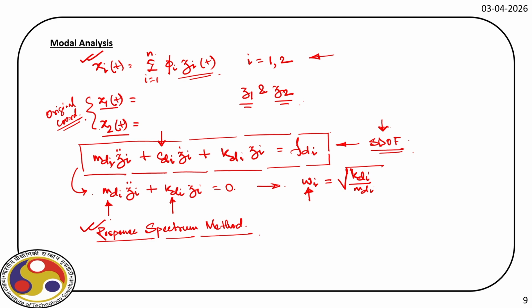If you recall, earlier we defined the stiffness because we developed the model in STAAD using 3D beam elements, as you have seen. And then once we developed the model with appropriate cross sections and material property, we applied static loads. So we applied the gravity load, we applied the floor load. We did not model the floor slab in our analysis because we kept it simple so that you can follow.